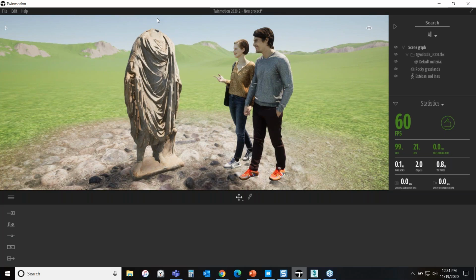But basically, tying this all back together, we can take a point cloud and bring it into Revit. Using a program like CloudWorks, we can create a 3D model from that. Then, if we want to make a really nice visualization, we can push that 3D model into Twinmotion, start to assign materials and different assets to the space to visualize it.